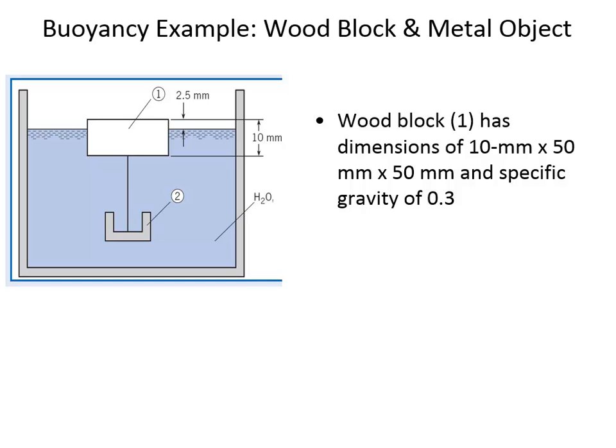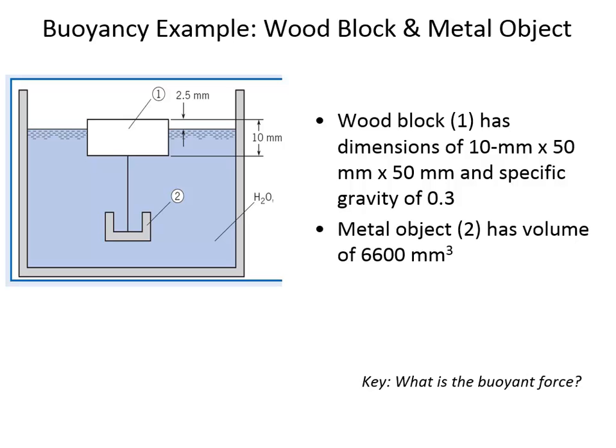The direction that our analysis is headed in is we're going to compare the difference between how submerged it should be and how submerged it is. And that extra amount of submergence is because of the weight of that metal object beneath the water surface. And so from that, we're going to be able to find out the weight of that object too, based on the difference in the buoyancy that it ought to be and the buoyancy that it is.